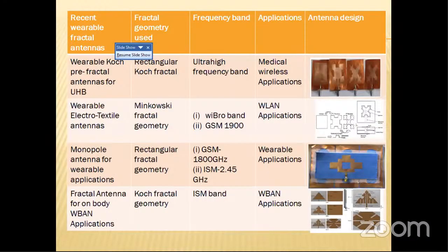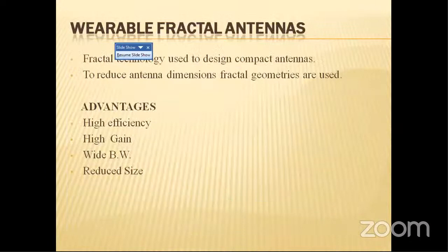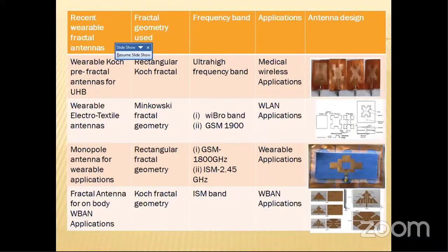Now we have different antennas designed by different researchers. These are wearable fractal antennas divided in terms of frequency band, application, antenna design, and fractal geometry. The first one is a recent wearable antenna, which is a wearable Koch fractal antenna for ultra-high band frequency.